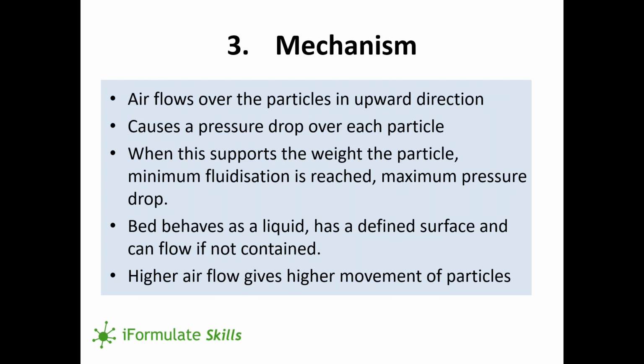So the critical bit then is to get the flow rate such that you get the pressure drop to equalize the pressure caused by the weight of the particles. And if you increase the flow of the air through the bottom, what you do is you make for more motion of the particles, but you don't get much more benefit from it because you've already fluidized the particles. In the next slide then,